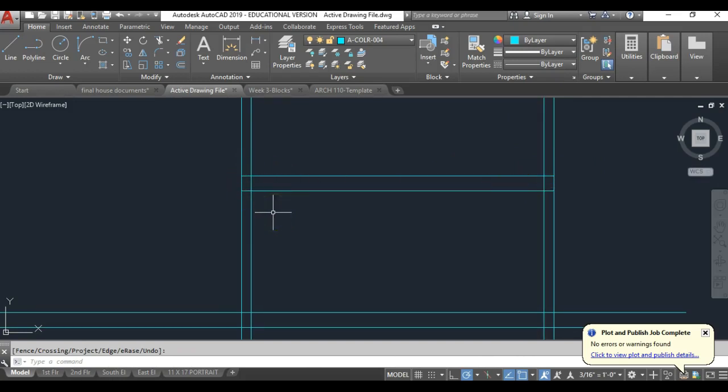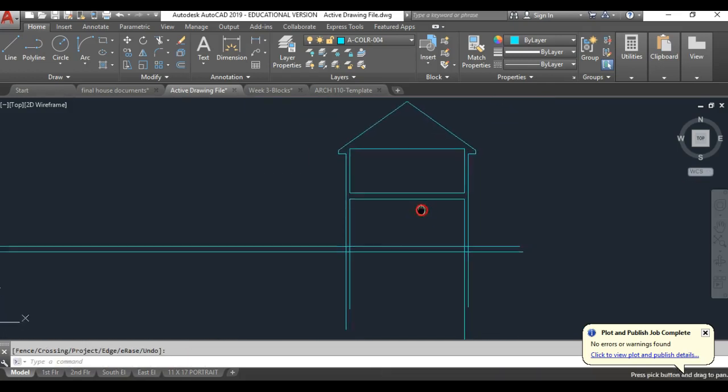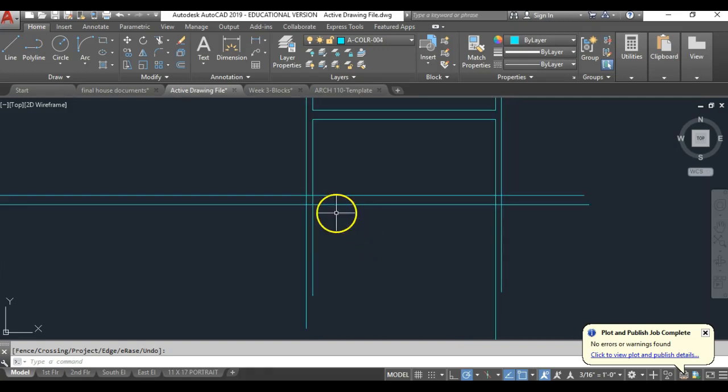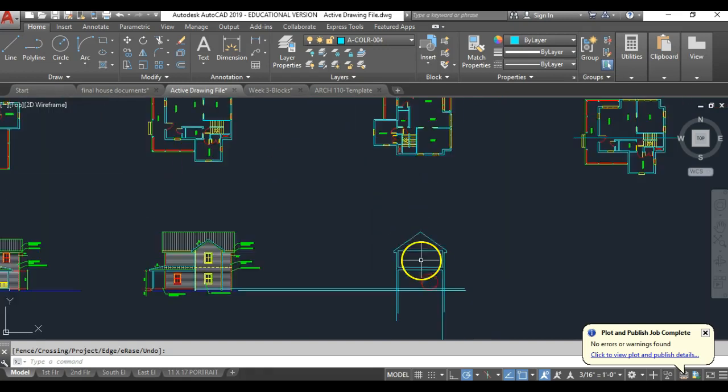Just like when you cut, you connect all the cut pieces together in a drawing like this. So I'm going to go to trim again and hit enter, so I can just make everything a cutting edge and trim that across there, and trim this all across here and here, and hit enter. And we can see we got the top portion of that. We already have the first floor done. So to find, and I can trim this out, but it actually has porches on each side of it, right?